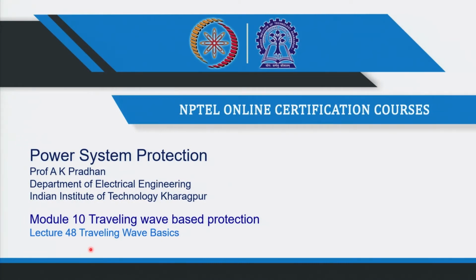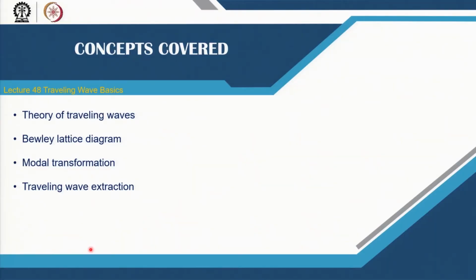We will continue with a new module on travelling wave based protection. In this lecture, we will discuss the basics of travelling waves, where we will address the theory of travelling waves, Bewley's lattice diagram, how modal transformation is carried out for this purpose, and then how the travelling wave is extracted and some of the features which we think will be resourceful from a protection perspective.